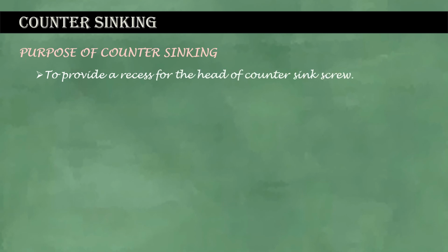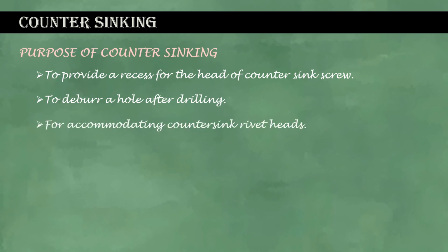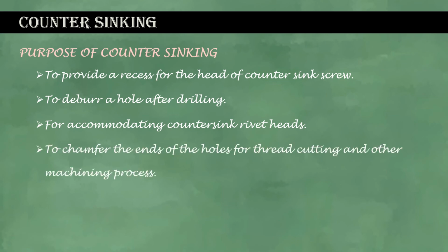Countersinking. Purpose of countersinking: to provide a recess for the head of countersink screw. To deburr a hole after drilling. For accommodating countersink rivet heads. To chamfer the ends of the holes for thread cutting and other machining process.